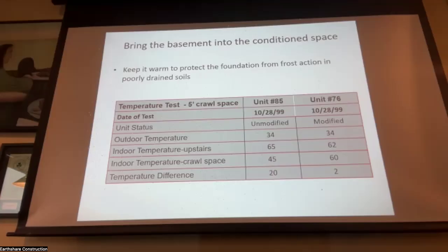But I didn't differentiate between stone, rubble and poured concrete simply because I was making such an improvement. I've done blower door tests on these wall spaces, and the numbers were so big that that was the benefit, in my opinion. Like I was telling you about, when we inject a wall and the cavity is only 3/4 of an inch thick, you're not getting much R value.